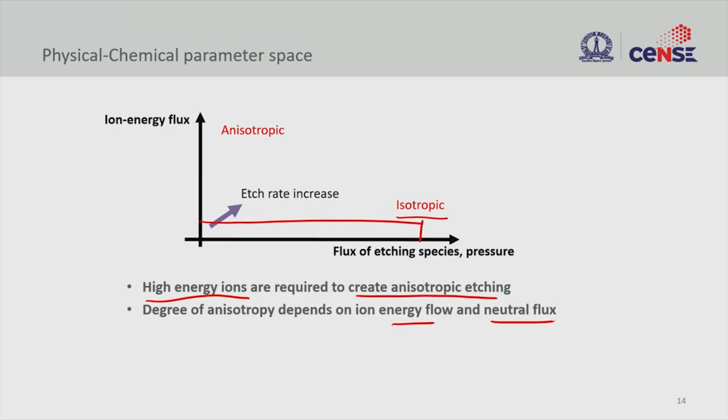But if you want to have high energy ions with a reasonable flux of etchant, you will have anisotropic etch. And if you want to increase the etch rate, you should move in this direction.